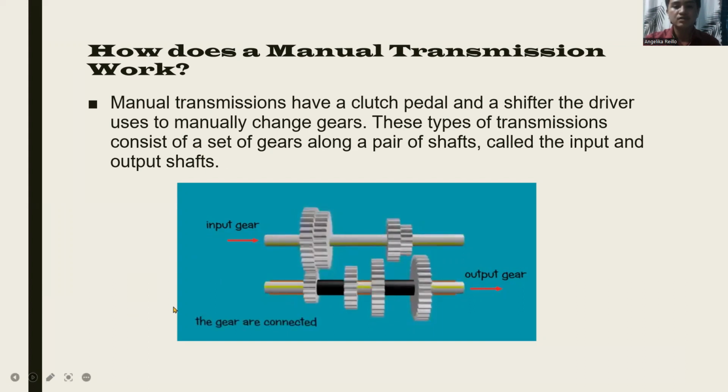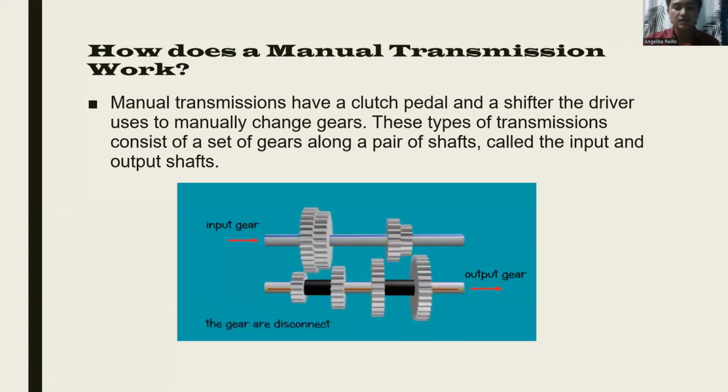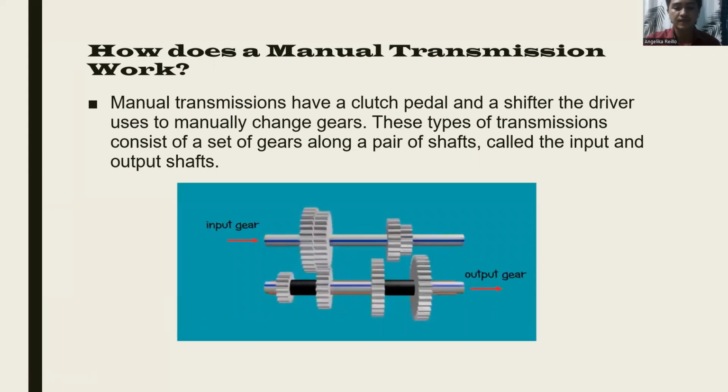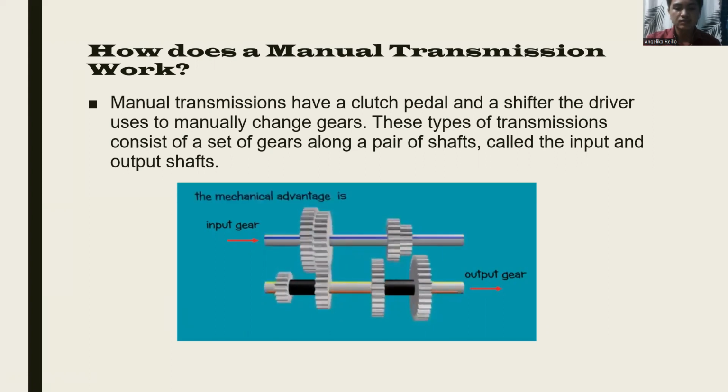With a manual transmission, the driver has to select the proper gear and engage or disengage the clutch. The transmission uses a flywheel, pressure plate, and clutch to engage and disengage the engine from the transmission. The flywheel and pressure plate are connected to the engine. The clutch is sandwiched between them and supplies the transmission input shaft.